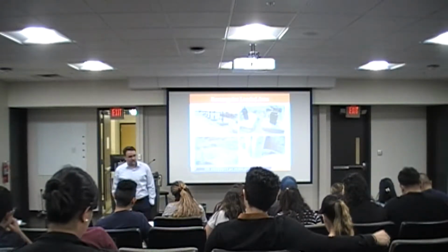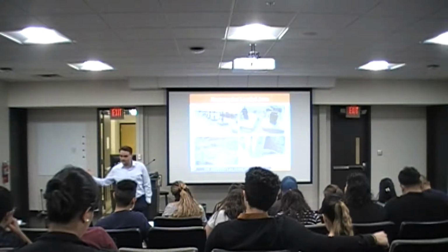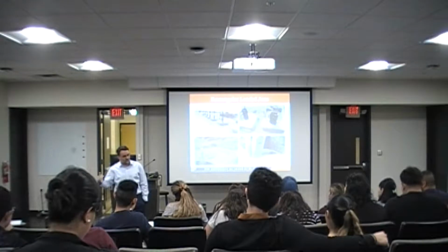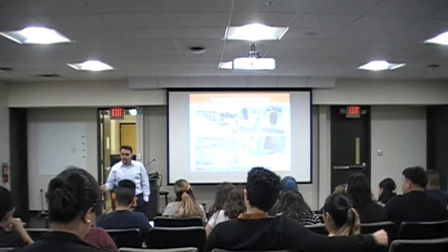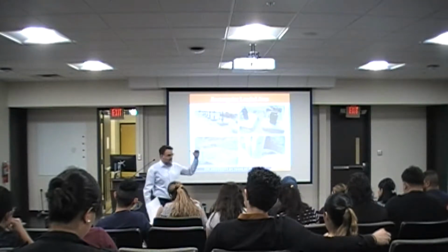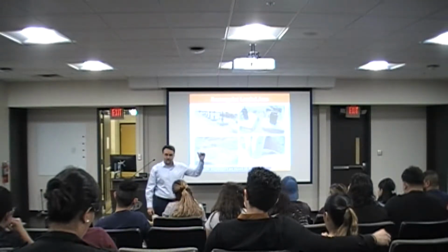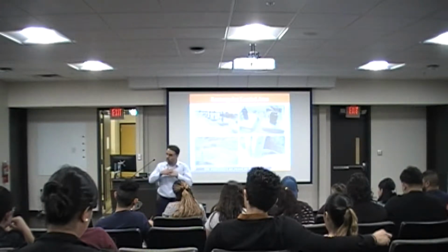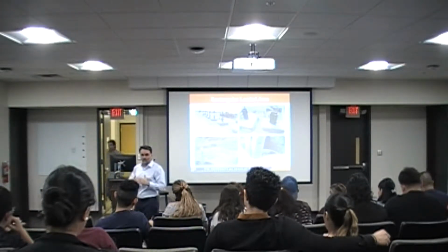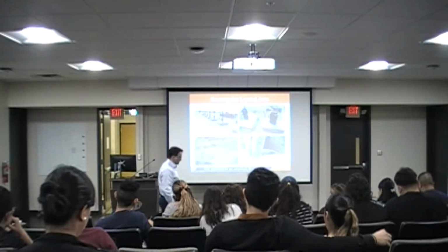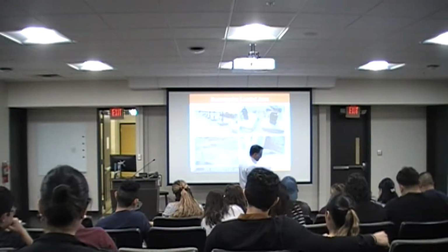Alright, in terms of the stresses, remember from your geostatic stresses, the magnitude of the stresses are progressively increasing with depth, but it was in reverse when you're looking at the external loads, right? The highest magnitude of the stresses were happening at the interface or contact, and then it diminishes with depth and with radial offset, right? So those were the differences in terms of the distribution of the stresses.